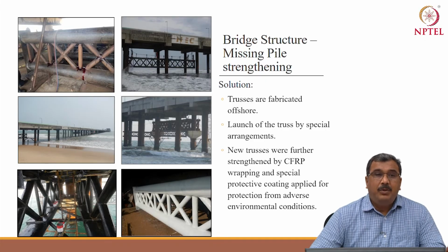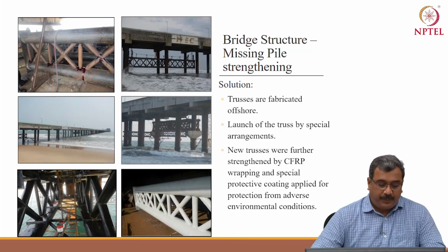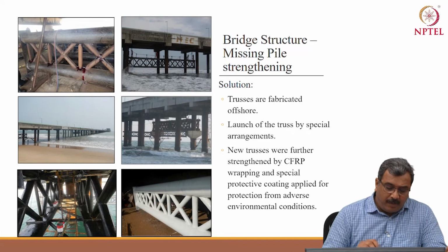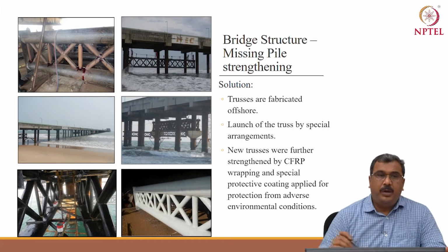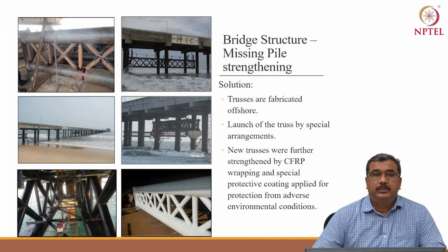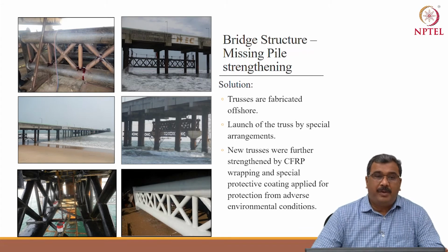There will be an insulating coating in the form of epoxy, which will not allow electrons or ionic parts to travel from carbon to iron. No direct contact. After carrying out carbon fiber strengthening, a further protective coating has been applied on the carbon fiber system.